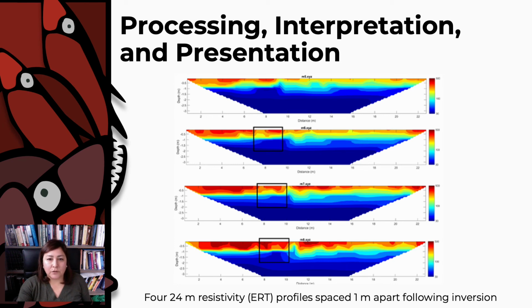To transform resistivity data into 2D profiles and then plotted into 3D grids, the data must undergo a process called inversion. Most commercially available inversion software will automatically calculate the best resistivity model possible for the electrode configuration with minimal user input. Once this is done, processed resistivity data can be gridded and visualized in different software options, such as Surfer or a GIS.